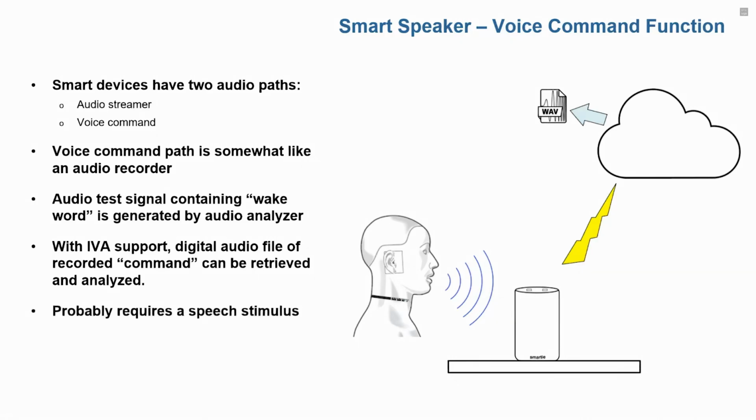Now this probably requires a speech stimulus because many of these devices have DSP inside them that prevents passing things like sine waves and noise. And in this case, you can't use a sine signal to test the device, so you probably want to use a speech stimulus.